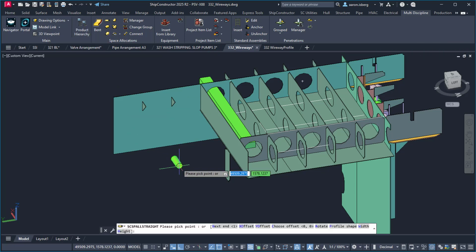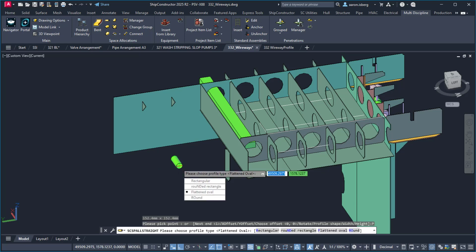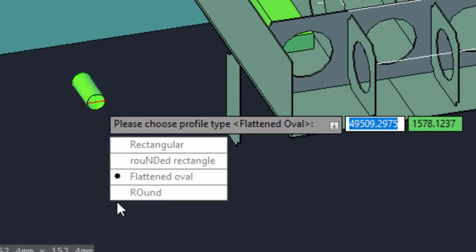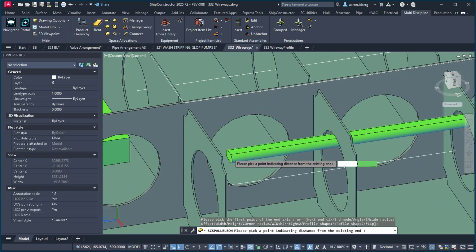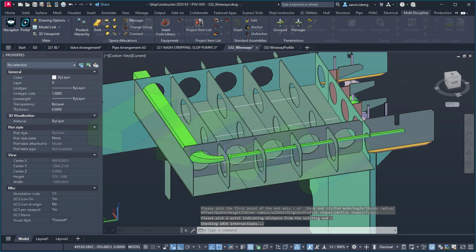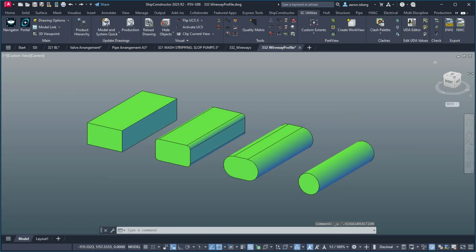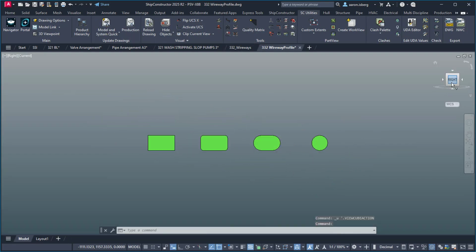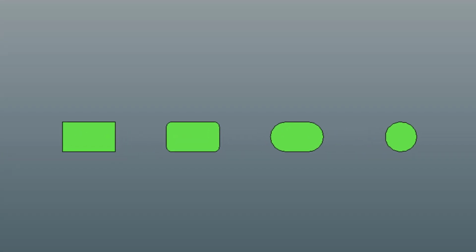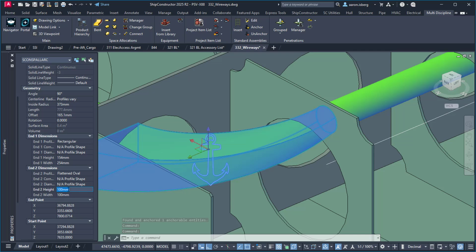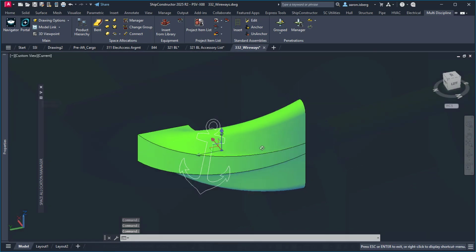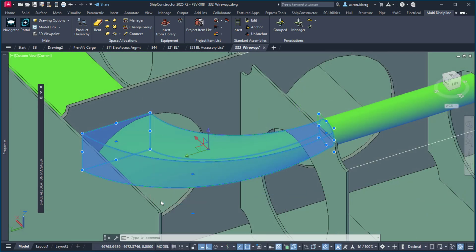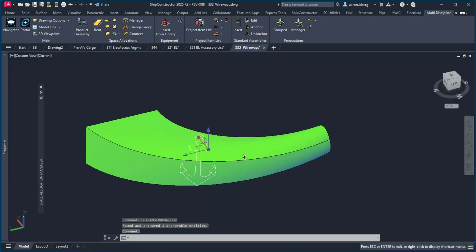In alignment with ongoing efforts to improve space allocations comes the ability to accurately represent shapes and profiles, leading to a more efficient workflow within the functional to detailed design modeling process. Space allocations now include the following profiles: standard rectangular, rounded corner rectangular, flattened oval, and round. Furthermore, space allocation context menu options provide customizations for profile corners and their transitions, and include constraints for grip edits, preventing invalid shapes from being generated.